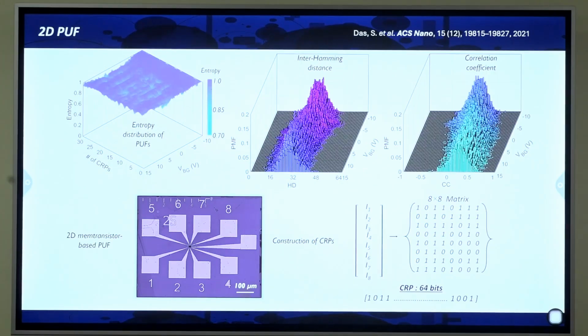I feel like this is something a lot of you who are working with materials can actually do. And it doesn't always have to start with IV characteristics. You can also use Raman, PL, XRD data in order to create that PUF. Because if you measure the same device, that's the same material that you're synthesizing, and take the Raman at different locations, the Raman peak position will be slightly different, right? And there have been papers where people have actually used that to create physically unclonable functions.